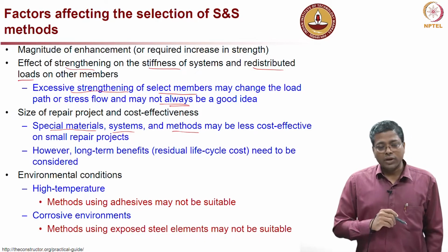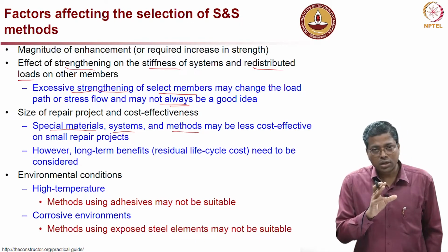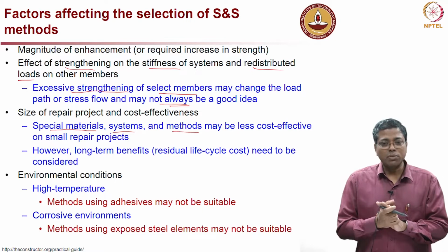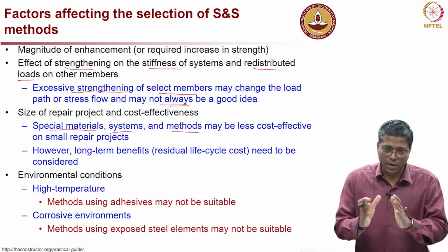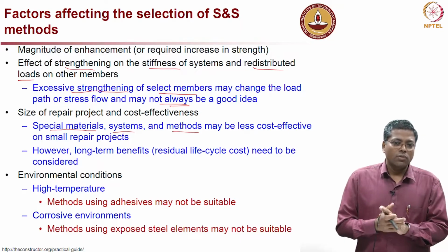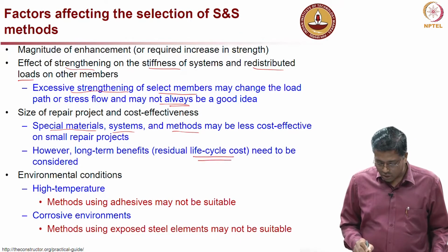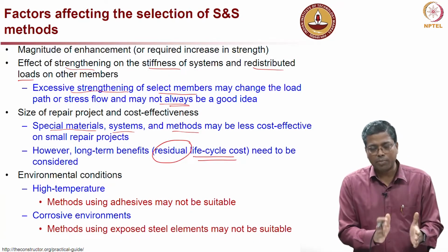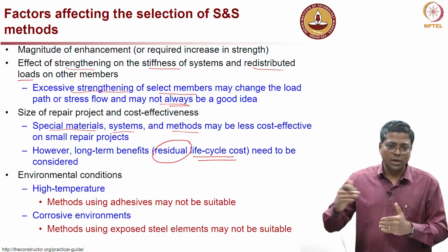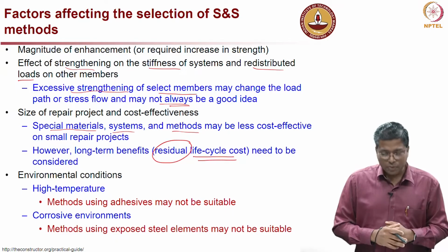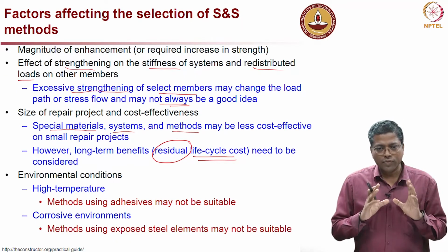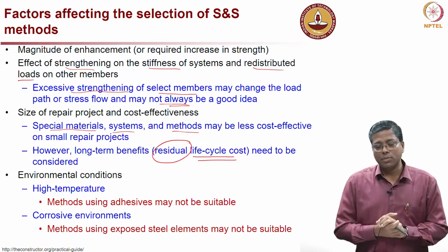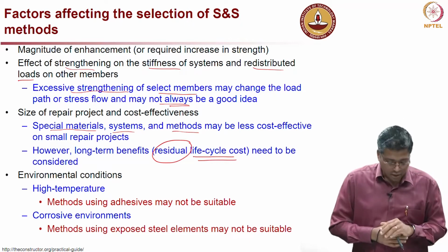But when you talk about cost effectiveness, it is not the effectiveness of the capital investment, and when I say capital here, it is for the repair, not the original construction. What we need to look at is the impact on the residual life cycle cost. Whatever happened, we can't do anything about it, but at least for the rest of the life of the structure, we can go for the best repair methodology, which will give you the minimum life cycle cost.